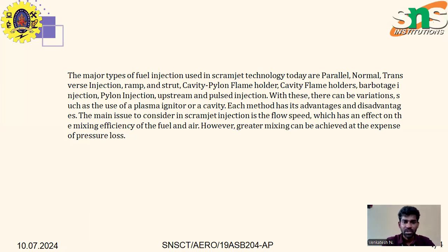The main issue to consider in a scramjet engine is the flow speed, which has an effect on the mixing efficiency of the fuel and air. However, greater mixing can be achieved at the expense of a pressure loss. So this is the overall explanation of the fuel injection in scramjet engines.